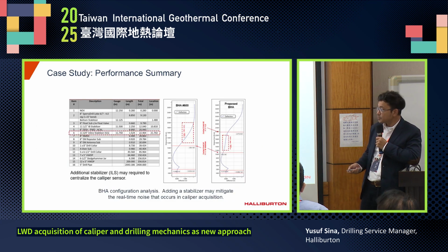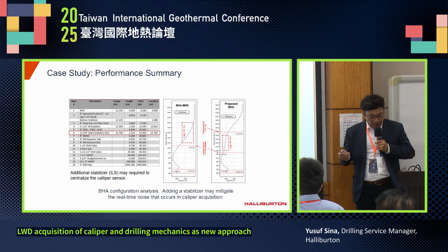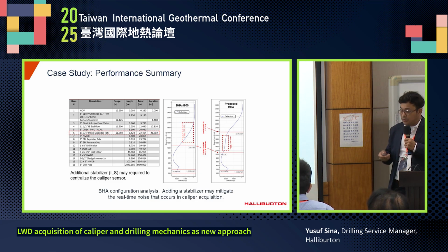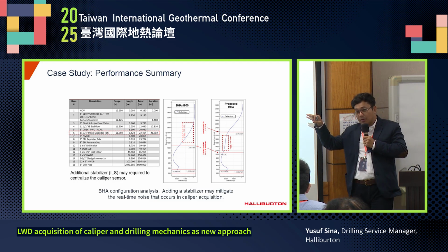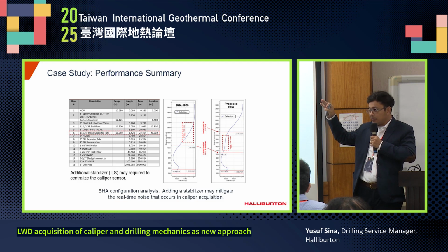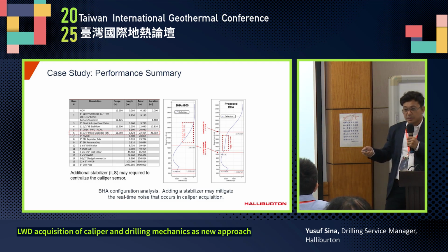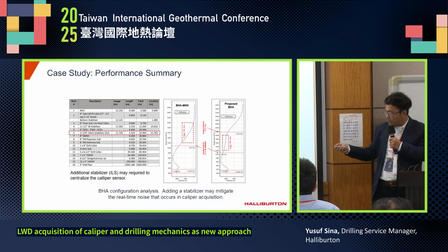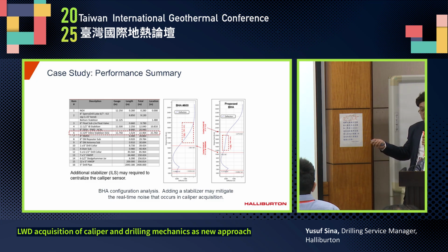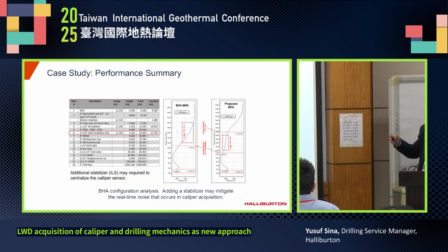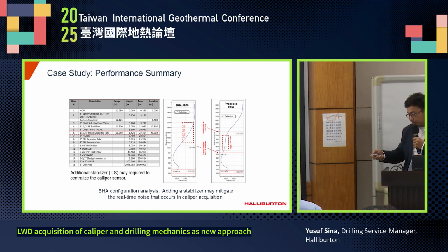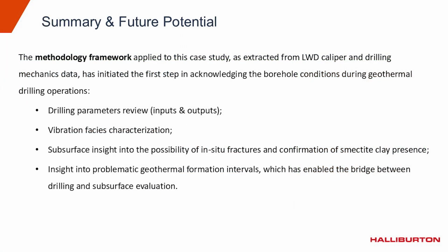vibration sensors, right? And then for a future application, we also realized that during drilling, we only have one stabilizer just below the acoustic caliper collar. So all the noise that we see before is coming from this poor stabilization, right? So for the future, we plan to have an additional stabilizer on top of the acoustic collar, so we can also reduce the noise during drilling, right?